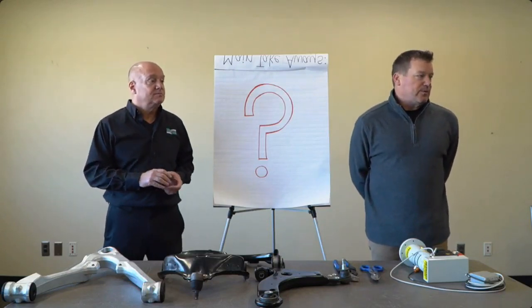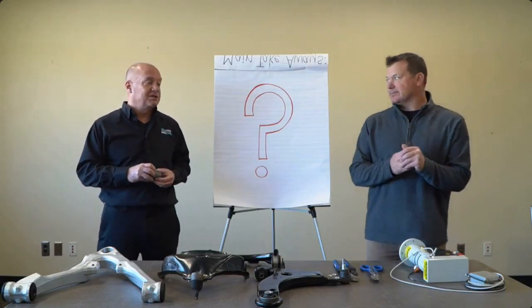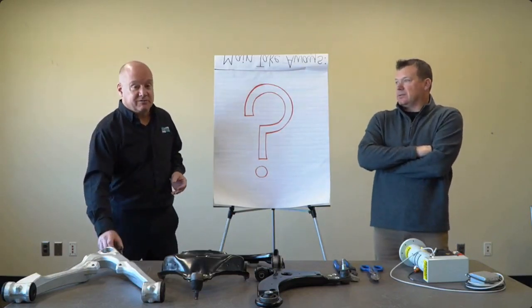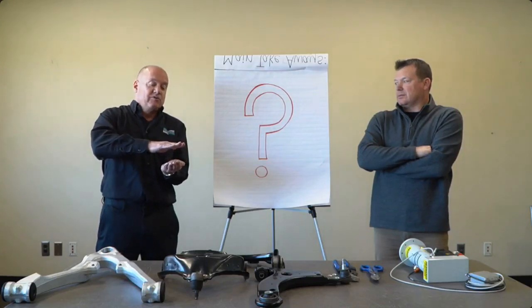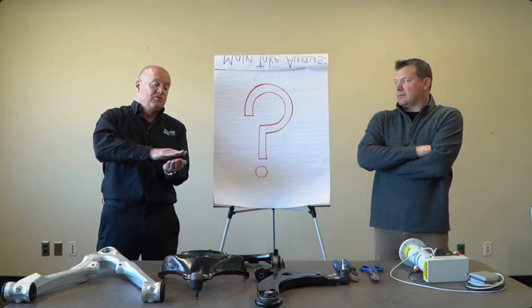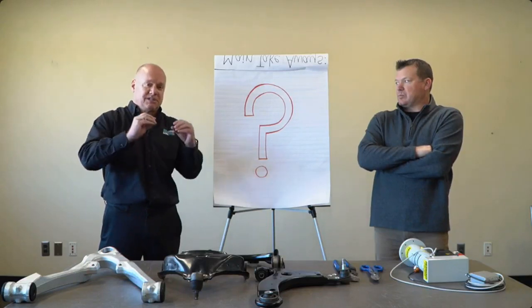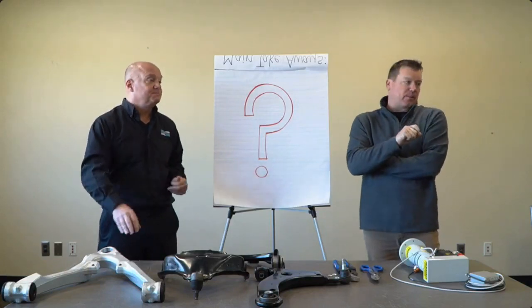Can you hold a force until a temperature is reached, for example? Yeah, that's no problem. We've done bearing quenching and other types of applications like that. It's pretty common for us. Some parts move around as they heat up or cool off, and you want to hold a force. The press is designed to move and not hold a position while cooling. If you program it to 1,000 pounds, it'll move around and continue to hold 1,000 pounds as the part expands or contracts. So it can follow the part if need be.